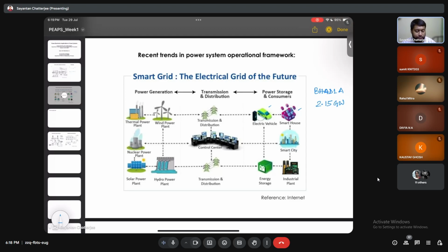Most of the renewables that we see, when we see a solar power plant, a solar power plant is full of inverters and converters, and these things need to be controlled properly. And all these things have a very fast response. Switching time is very fast. So accordingly, things need to respond in the form of reactive power compensation, where the voltage profile needs to be improved.